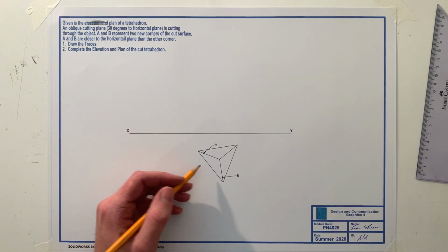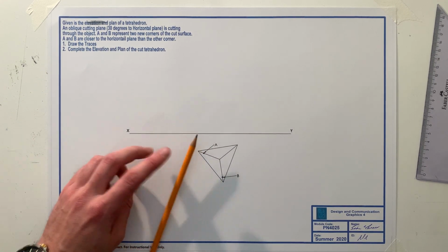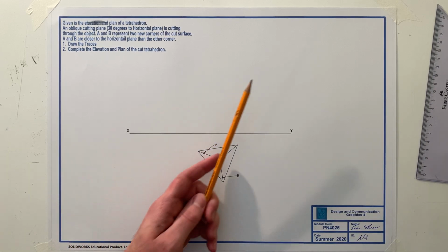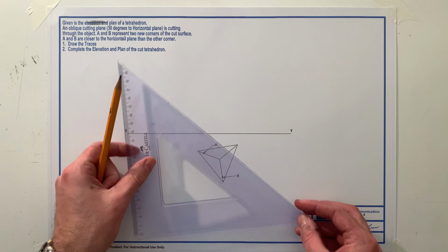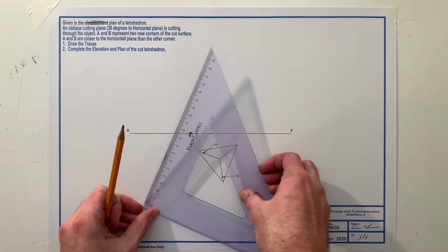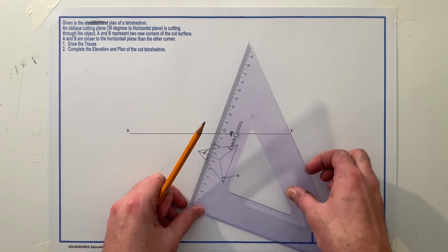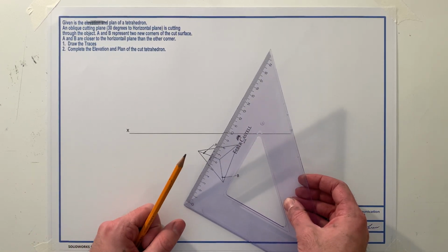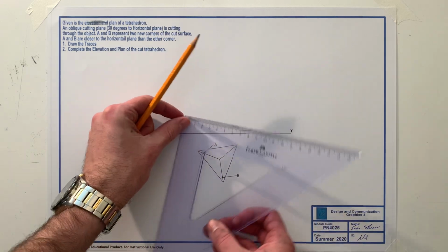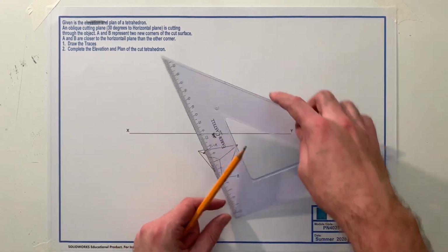Okay, so we have our object here. We have a cutting plane which is cutting through this object, and it's cutting through it at 30 degrees. Now we don't know at what angle it's coming from. We know that it's 30 degrees from the horizontal plane, but we don't know what angle it is to the vertical plane. So for instance here, we don't know if it's in this orientation or this orientation or this orientation